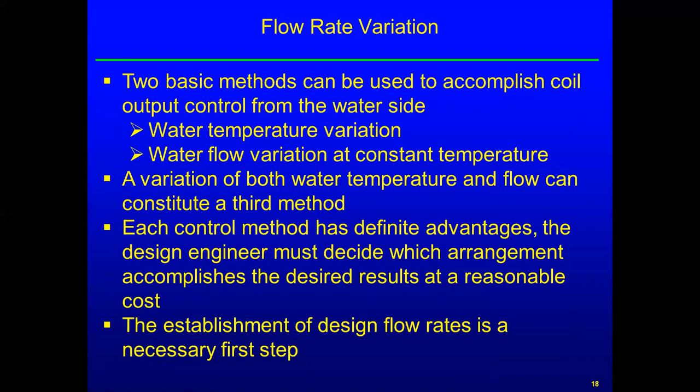So let's see, each control method has advantages. It's up to the design engineer to decide which arrangement he's going to select, and a lot of it has to do with a reasonable cost, as we'll see. Establishment of design flow rates is a necessary first step, so you have to do that no matter which of the two control schemes you're going to use, temperature or flow.